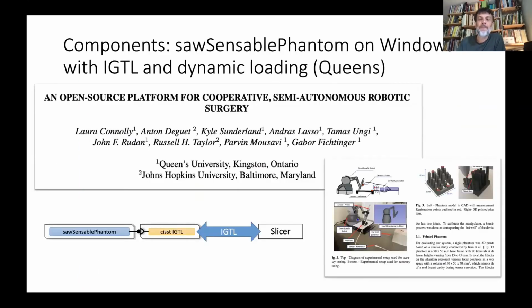The other thing that I want to mention is all this bridging code that we have, that is for ROS, for IGTL, or anything, is independent of the device you put underneath. So now if you decide to use Phantom or any other force sensor that we currently support, or any other arm that we currently support among the SO components, you can reuse all the bridges. So the good thing for me is my Omni, my ForceDimension, my Atracsys, my Polaris, because they are already SO components, the minute I have ROS2, they become ROS2 devices in about half an hour of coding.